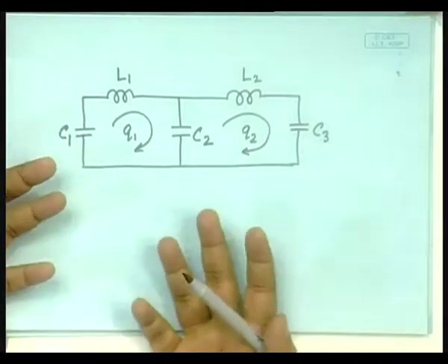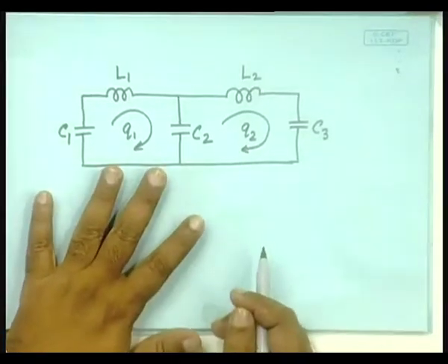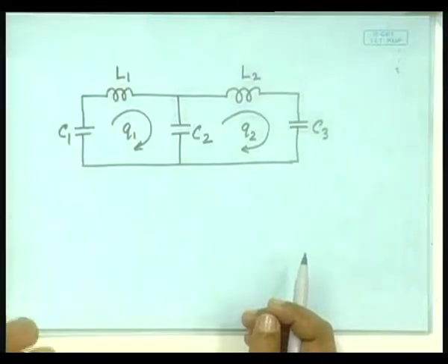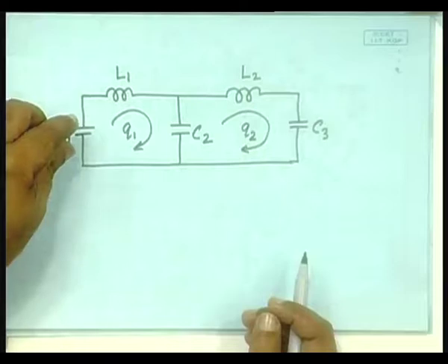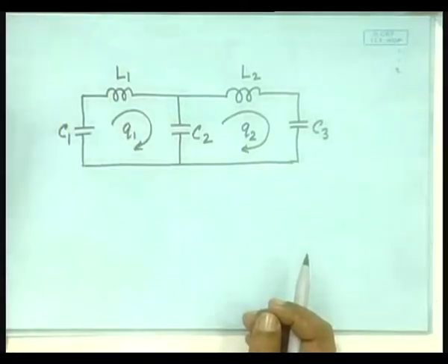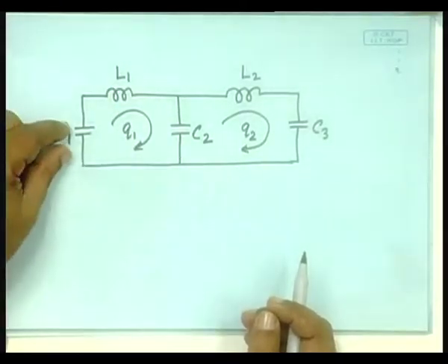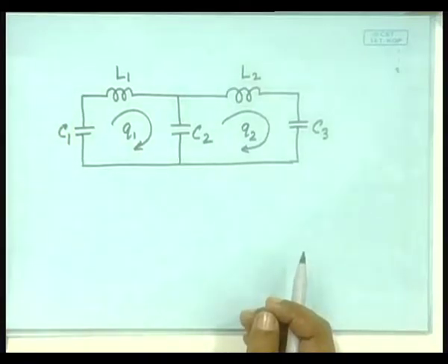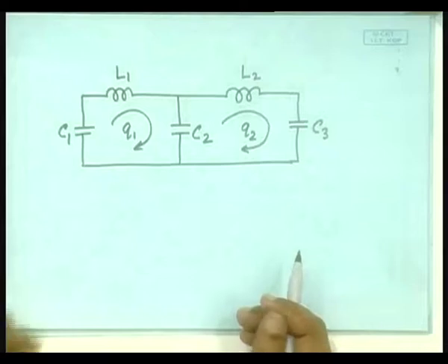In this case also we will have to write down the kinetic energy and the potential energy. What is the equivalent of the kinetic energy in an electrical circuit? No, not the charge, the energy stored in the inductor, that is the equivalent of the kinetic energy, and the energy stored in the capacitor is equivalent to a potential energy, because the capacitor has the character of being a compliant element equivalent to a spring, that is why we have to do it that way.